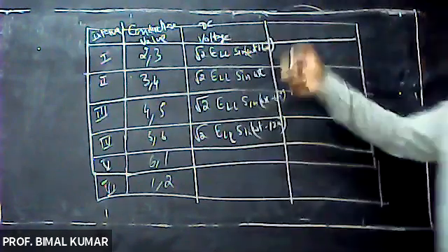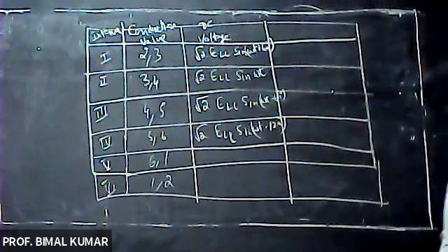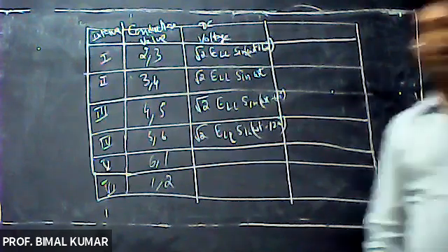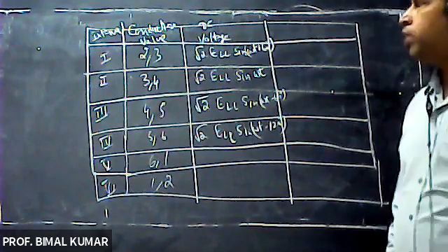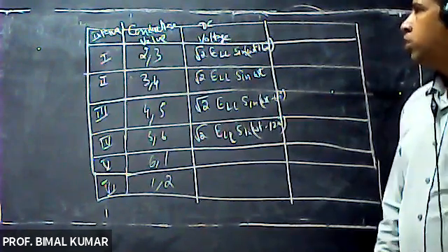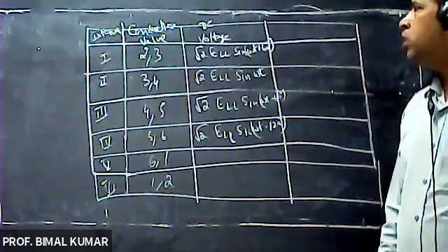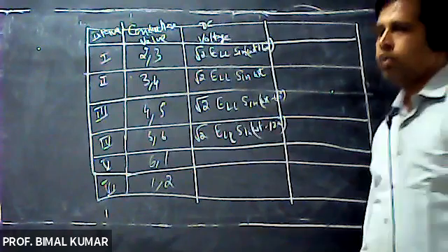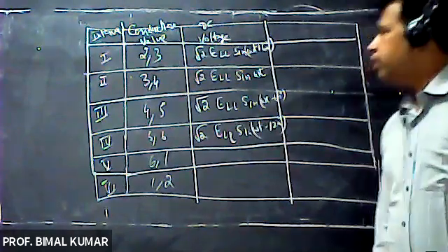Right? So each will be just departed from the first one at an angle of 60 degree. Right? Because in the timing diagram we had already seen there is a phase difference of 60 degree, or each valve pair will conduct for a 60 degree time interval.